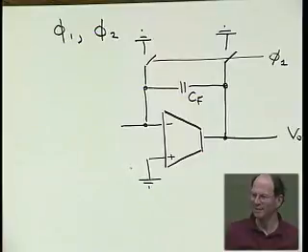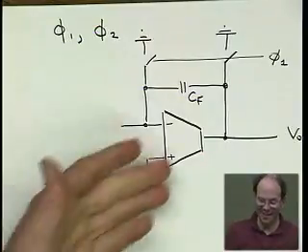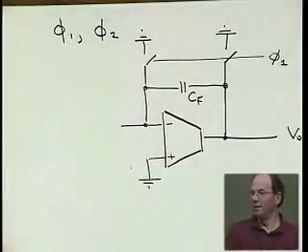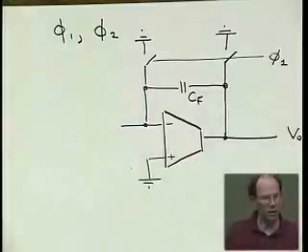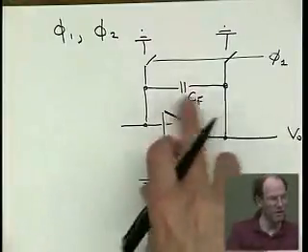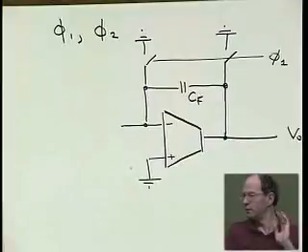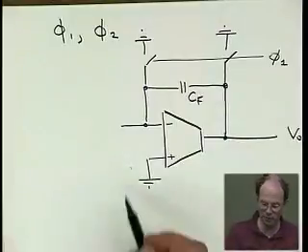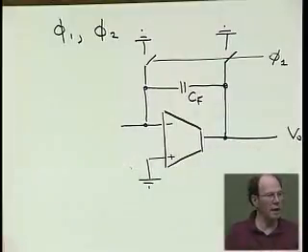Michele, right? Yeah. Because it acts like a current source. So right, exactly. It's a current source. Of course we can short-circuit a current source. We just get the current of the current source coming out. Probably there is a diff pair with a tail current source set to 200 microamps, and the 200 microamps just flow into the output.